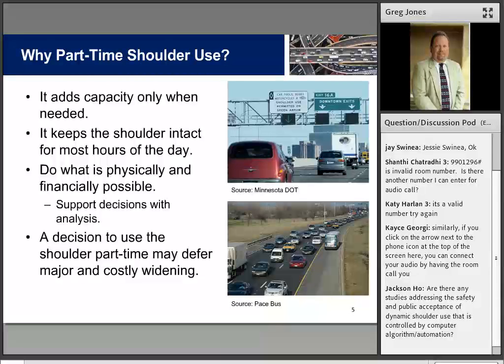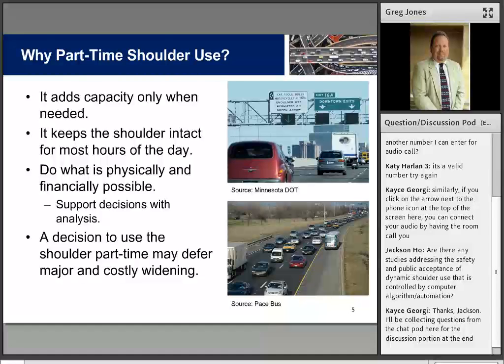At the times that you have congestion, by adding additional capacity, you can reduce the accident probability of congestion-related incidents. And those types of incidents are the rear-end types of incidents that happen in stop-and-go traffic. But when you look at that same roadway and you're outside of those congested conditions, really you're better off having that safety refuge when your vehicles are traveling at higher speeds. And that's the best safety solution for that type of application.